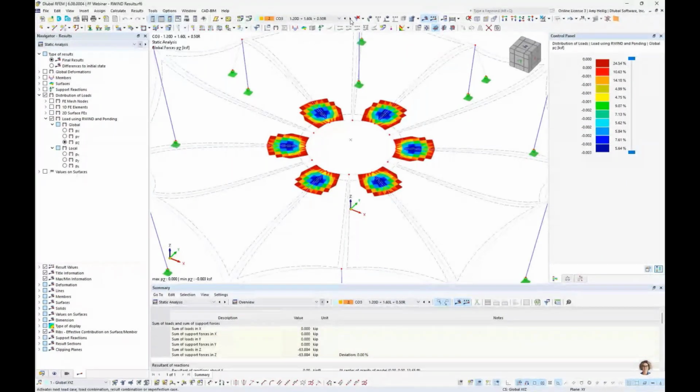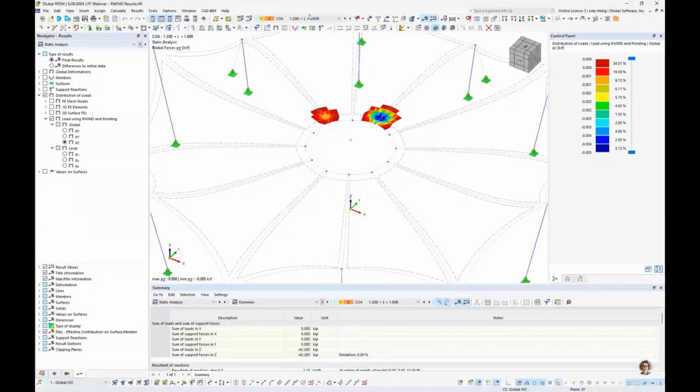But if we change here to a different load combination, which also includes rain, you'll notice that we have a different shape on our structure. So inevitably, maybe there are some areas that are prone to ponding where others are not, in comparison to the load combination before us. Again, this can be quite powerful as our structure changes shape and those different applied loads for rain accumulation.